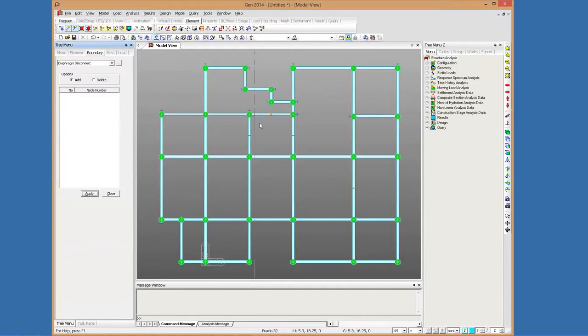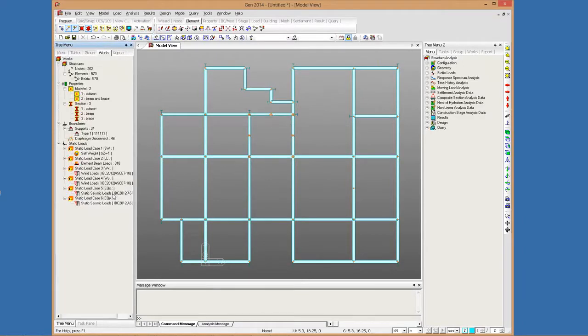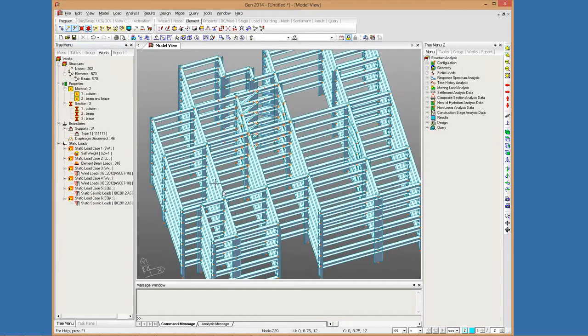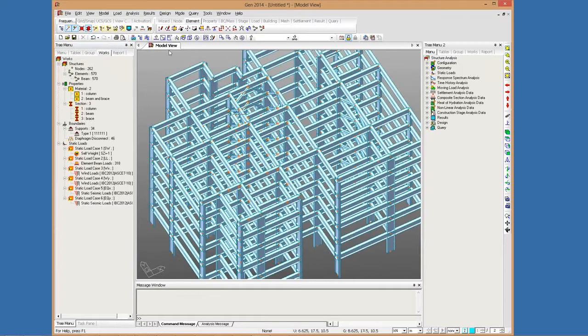So on using this option, what happens is you just select some nodes and apply it. So whatever region that is bounded within these nodes, that will be removed from the diaphragm. So it will be as if there is no slab in between these nodes. So the elevator shaft is clear. Similarly, if you have a staircase or a stairwell, you can directly use the diaphragm disconnect to model that as well.